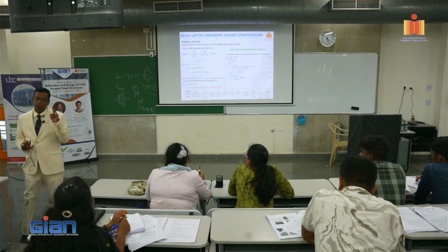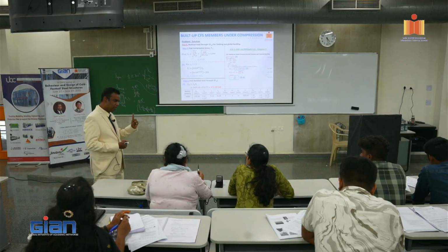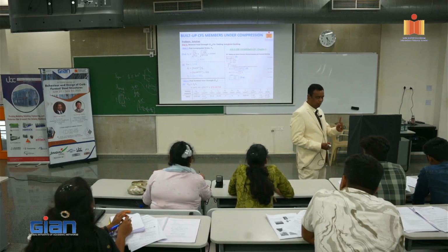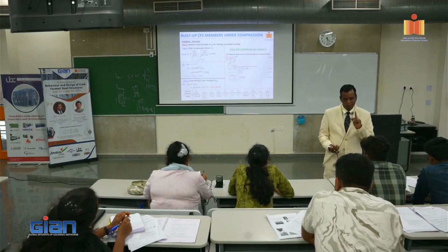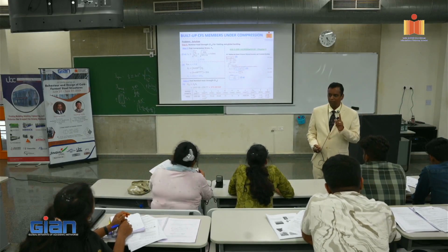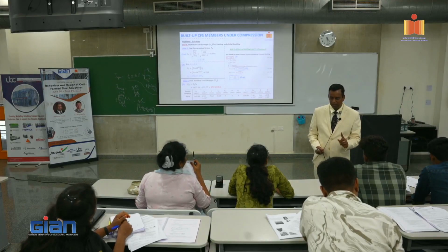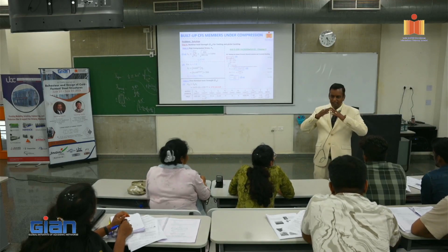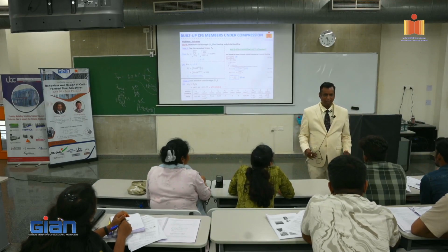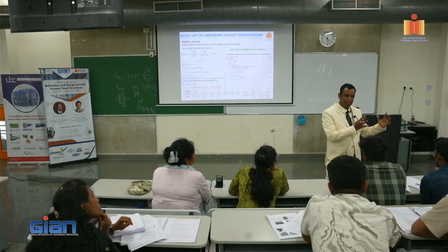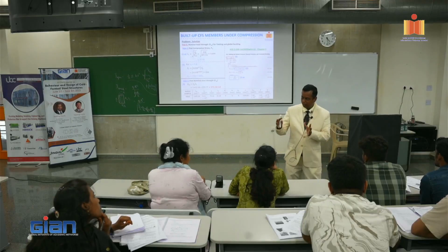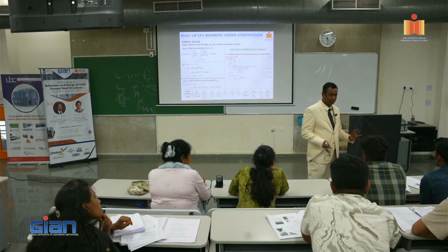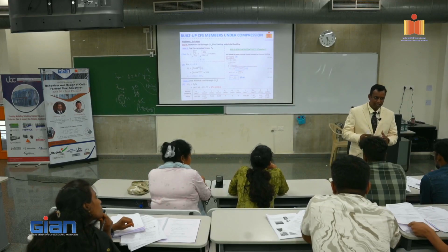Now two more things are there. One is nominal local buckling load. The third one is nominal distortional buckling load. But the second one, nominal local buckling load, is a little tricky. Why is it tricky? Because inside that there are two fellows. One fellow we can use the effective width method to arrive at. Another fellow we have to use the direct strength method to arrive at, and then we'll find out which fellow to use. You understand? So it's slightly getting complicated.